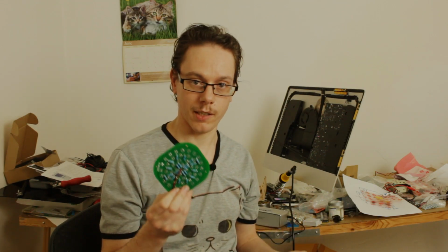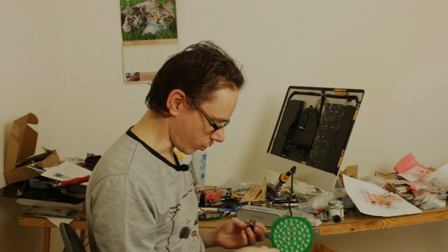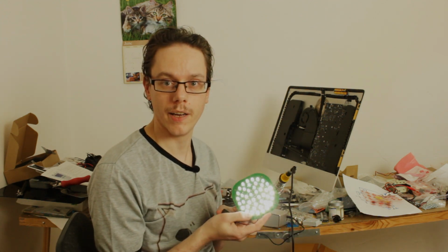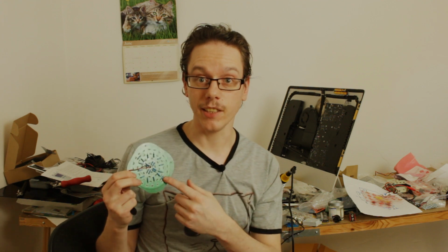This is an LED light panel that I've made. It's got 44 LEDs on it. And if I just hook that up to 9-volt power, you can see that works perfectly fine. And there were no issues with this during manufacturing. But I didn't hand draw these. I actually made these traces in Blender, so in a 3D program, and that just gave me much more control over the thickness of the traces and exactly where I wanted them to go and make sure my clearances were right, things that you can't really do when you're hand drawing it.